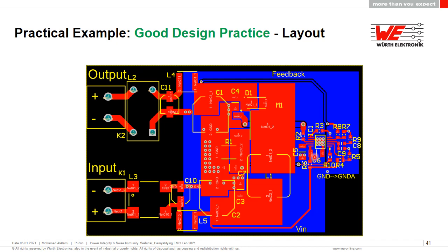So you minimize any noise or glitches coming onto the sensitive signals. That's very key, and this is another major change that we have done. So you can see we have implemented pretty much everything that we have talked about before, 1, 2, and 3: capacitors or component modifications, LC filtering, and layout and tracking.